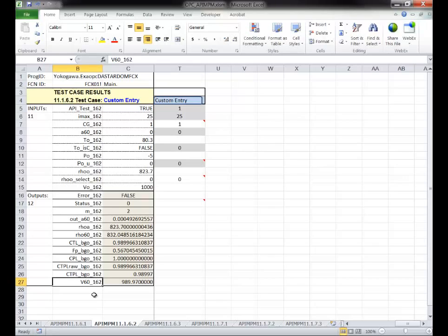And if it's a metric or any alternate conditions, then it would be like a VO for observed, volume at observed, or V sub A, which would be alternate conditions. So if you see a number there, a number like 60 means customary base, 60 degrees Fahrenheit. If it's a letter that's used, then the letter designates what the condition is. O being observed conditions, B being base conditions, generally metric base conditions versus customary base, which is 60, and then A is alternate conditions. So those are the naming conventions I've used, and this holds true throughout all the calculations and examples.